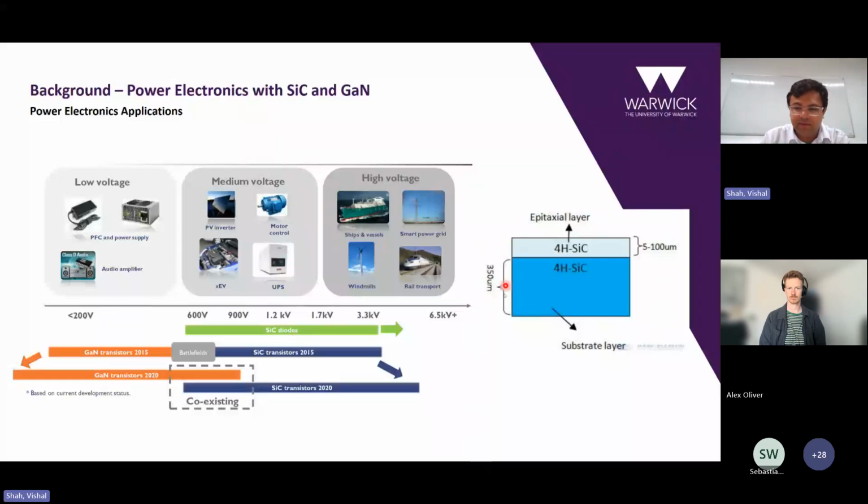But to boil it all down, the device is really reliant on this epitaxial layer. This is the layer which withstands a voltage in the off state. And it is the layer where, as I will talk about, the defects exist and they may start to affect device action.